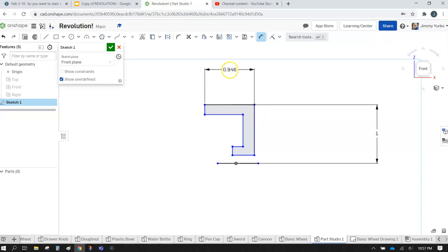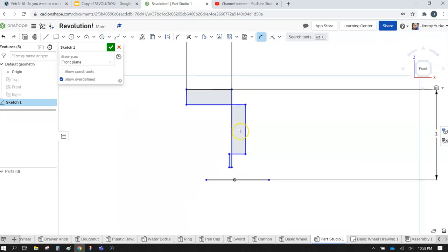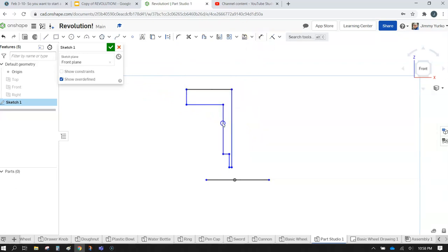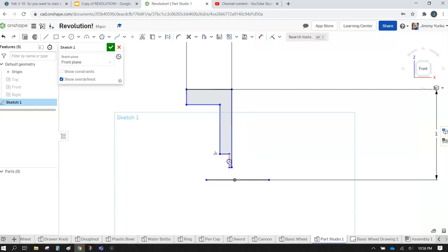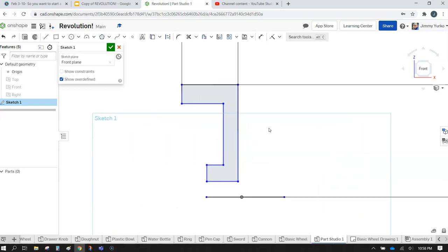I'm going to put my mouse up here in the center, and we're going to create a 1/2 inch thick tire tread, which you can see can sometimes create a goofy little scenario like that. No big deal. Hit the escape key to get out of the dimension tool, drag that over here, and drag that back into position. Sometimes that happens, sometimes it doesn't. No big deal.